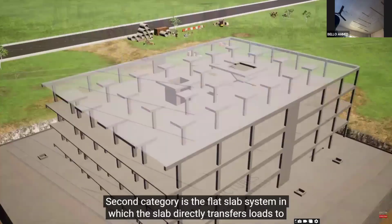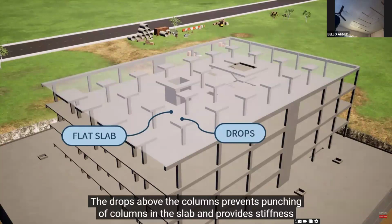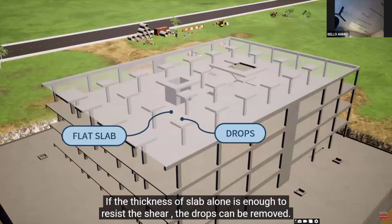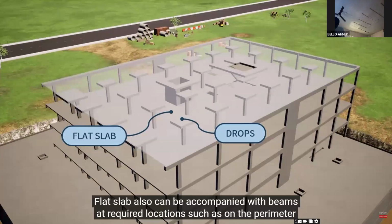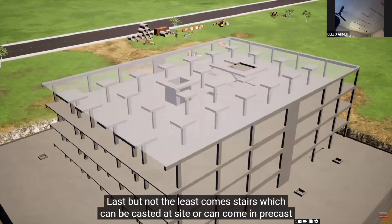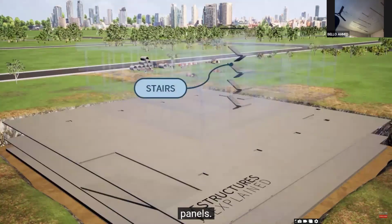Second category is flat slab system, in which slab directly transfers load to the column, having drops or without them. The drops above the column prevent the punching of the column into the slab and provide stiffness over that area. If the thickness of slab alone is enough to resist the shear, the drops can be removed. Flat slabs can also be accompanied by beams at required locations, such as perimeter of the building and around the openings.